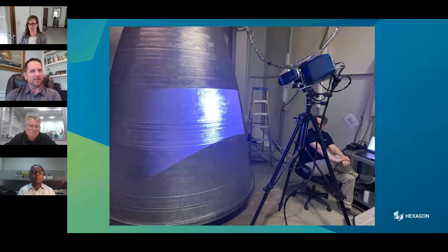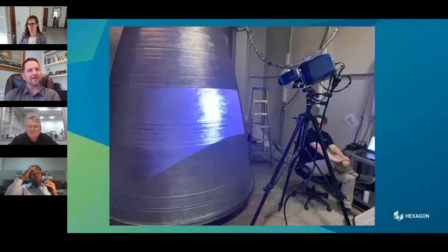So you can make some assessment about the volume of material that you're depositing, which is typically also associated with your feed rates of powder or wire, as well as the amount of substrate, whether that be the base plate on the first pass or subsequent layers on the subsequent passes, and how much remelting you're getting. If you can capture that, basically the fusion zone, and like I said, you have a good material model, then that is the majority of the calibration process. The physics kind of takes care of itself from there if you have good inputs.